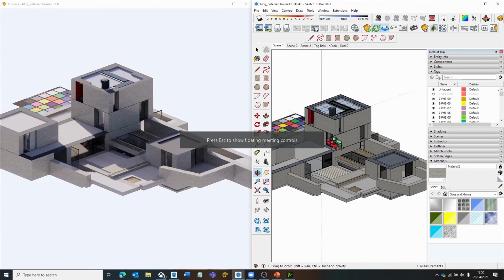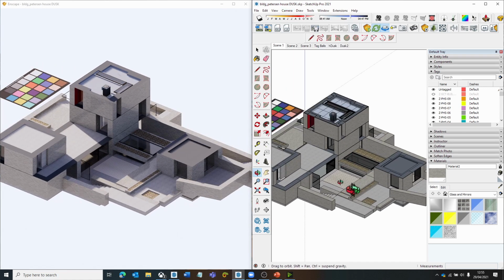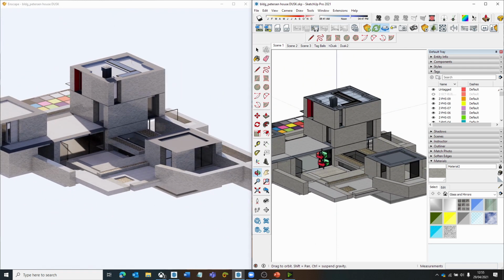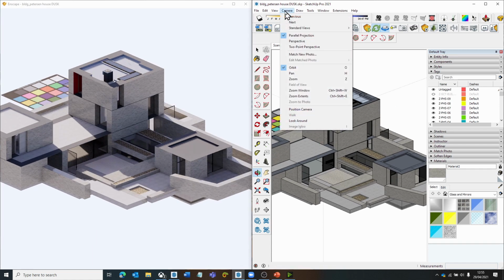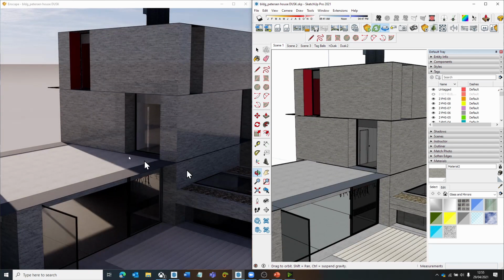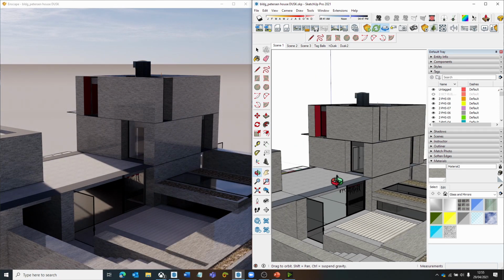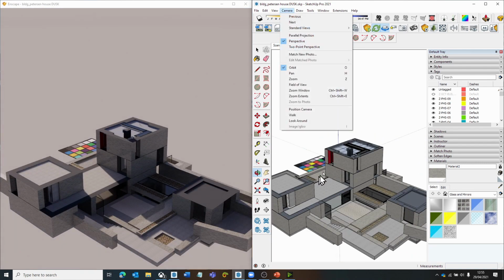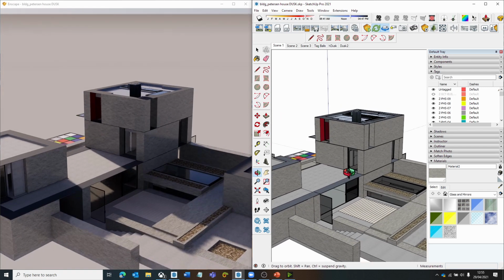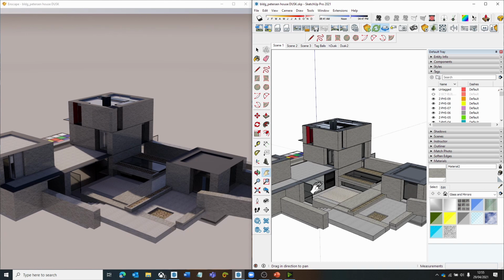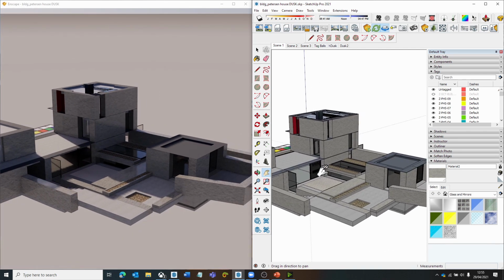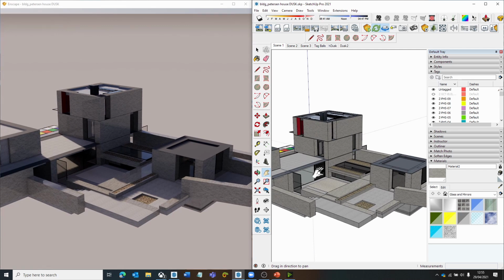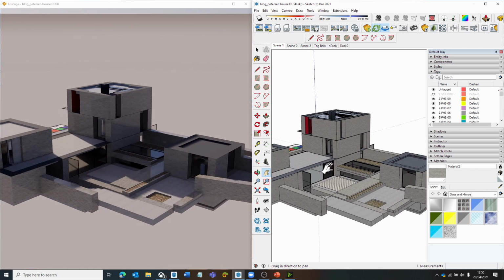Right, this is going to keep things in sync here. This will keep parallel projection perfectly aligned. If I rendered out this 2D image from SketchUp and rendered out a render from Enscape, those would remain exactly the same. Likewise for perspective. I can render this out, I can render this out, I can overlay those in Photoshop or something, and those will align perfectly. It's a little bit more complicated with two-point perspective. Unfortunately, Enscape doesn't recognize what SketchUp does. That's something that's being worked on, I believe, because that's been a request for quite a long time. There are ways to do it, so if you really need to know how, send me an email and I'll talk you through the process.